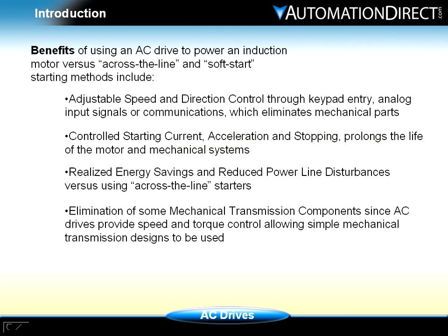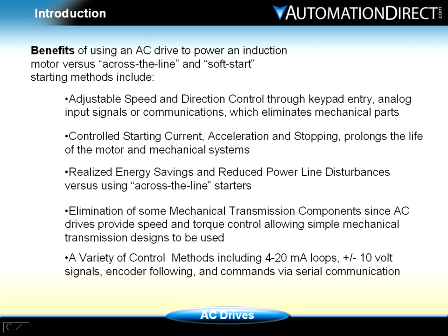Elimination of some mechanical transmission components, since AC drives provide speed and torque control, allowing for simple mechanical transmission designs to be used. And a variety of control methods including 4 to 20 milliamp loops, plus or minus 10 volt signals, encoder following, and commands via serial communication.